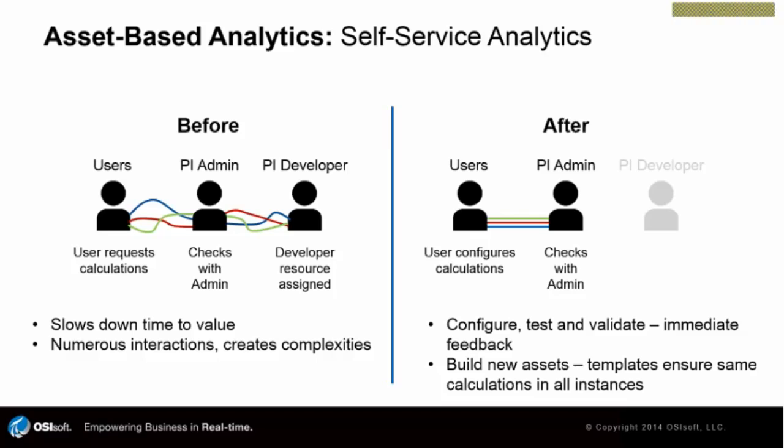As you saw, it's easy for a user to configure and test and validate the calculations himself. And all he needs is a final verification from the PI administrator that all the data is in place and that the system is set up to allow him to create these calculations. And with the use of templates, whatever the user does, if he does it at a template level, it's not lost, because changes to analyses at the template level are propagated to all instances from that template.